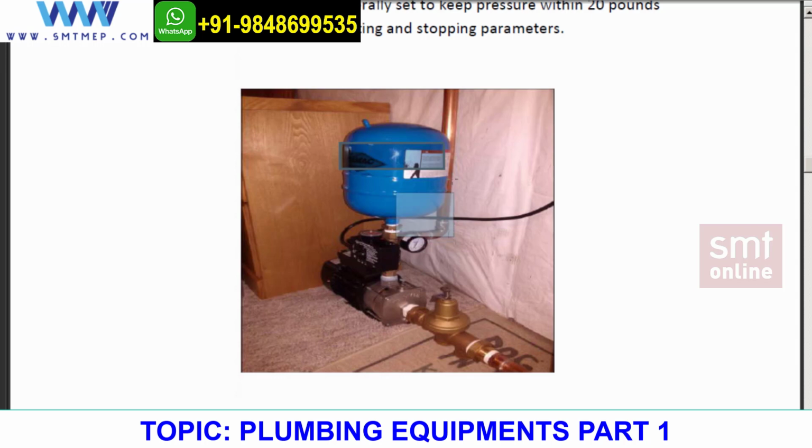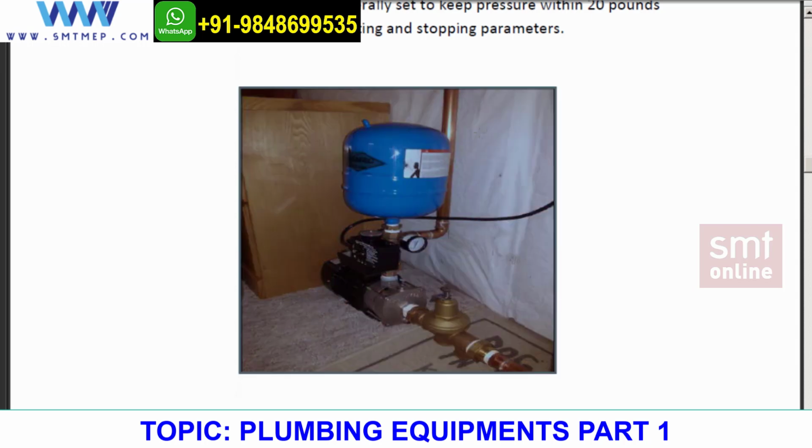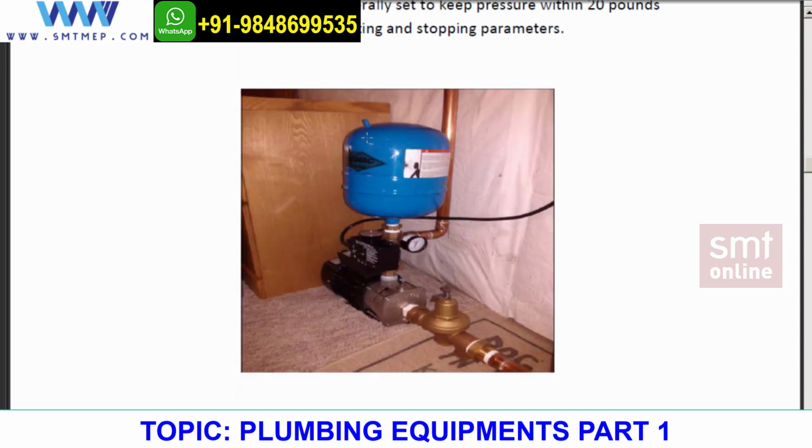So when it is filled, the water goes and pumps up to the respective fixture. What happens if it is not there? For example, if anyone is calling for any fixture 100 times a day on one floor, the pump needs to turn on 100 times for one floor. And if there are kids in the home opening this and that, the number of times the pump gets on and on and on increases. For the booster set, this is not at all recommended because we need to save the sources.